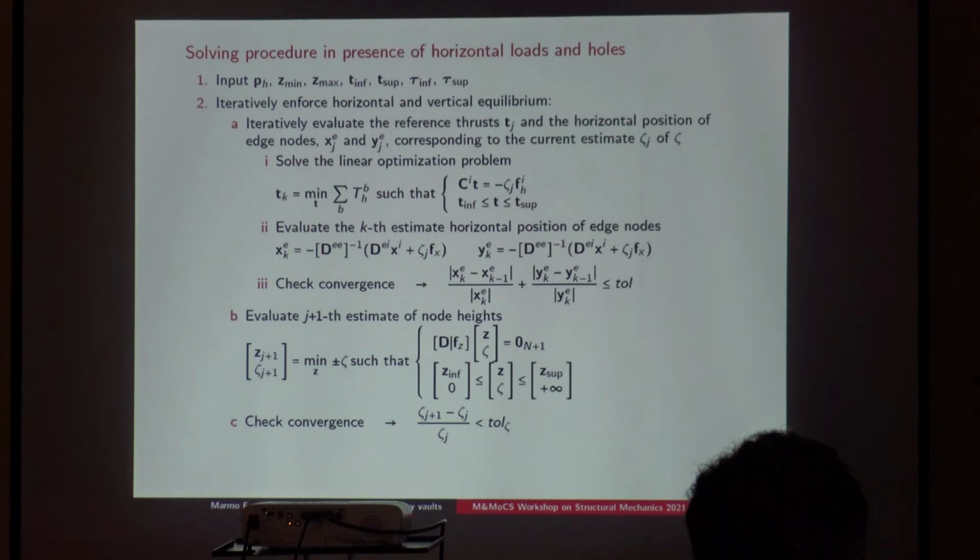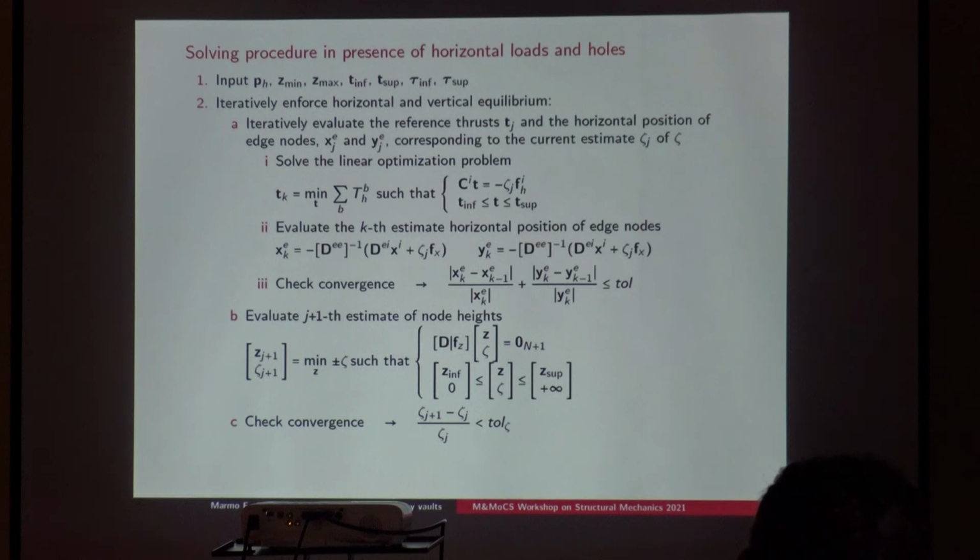The topology of the model can be related to the stereotomy of the vault. For example, if you expect to have some alignments of bricks, you can set your elements according to the orthogonal and parallel direction of the bricks, and so you can compute the solution. This affects the solution, yes. So you can somehow include the stereotomy of the vault into the solution.